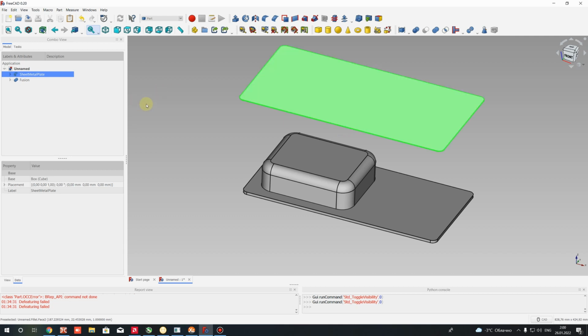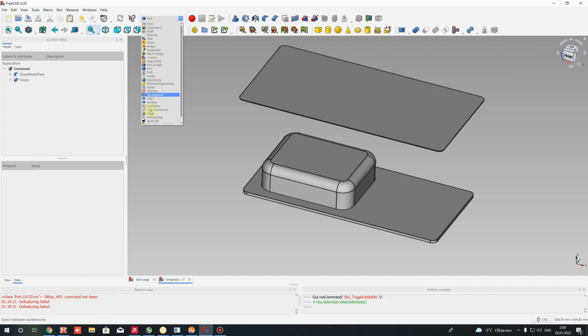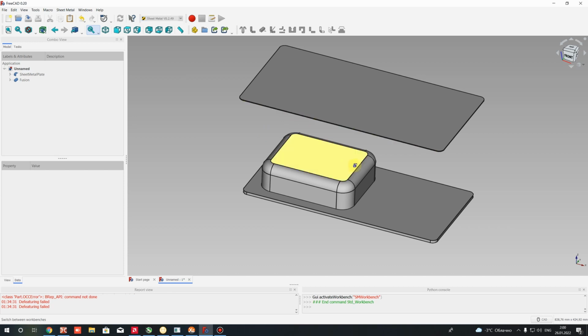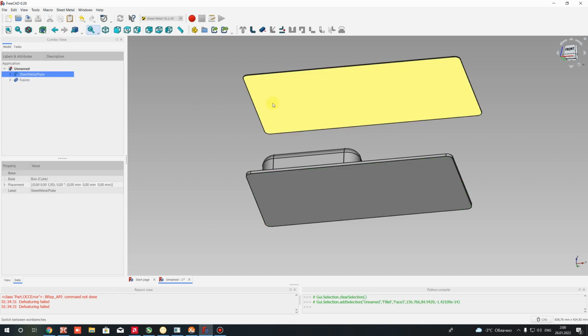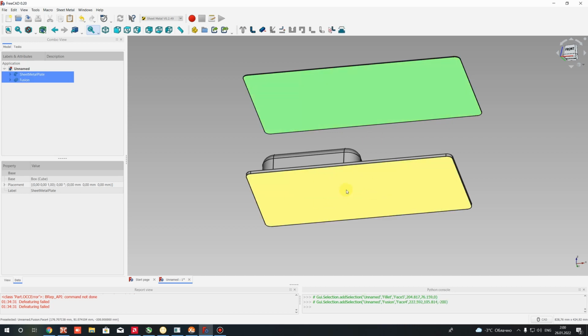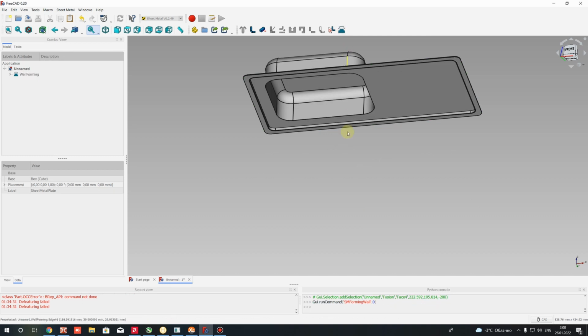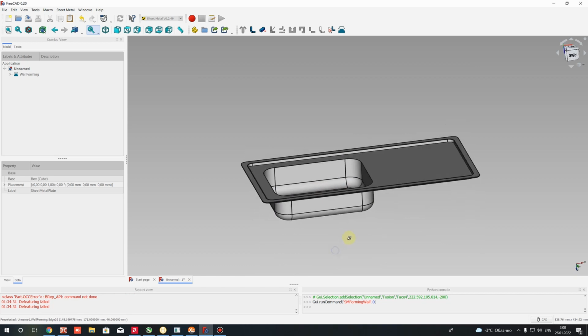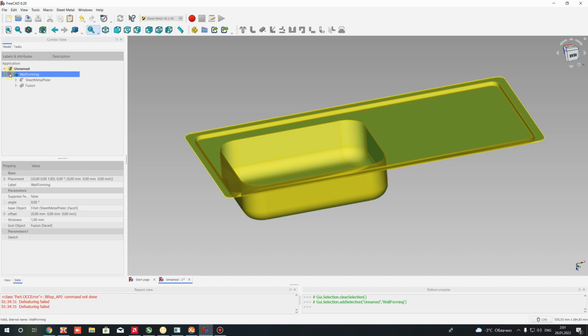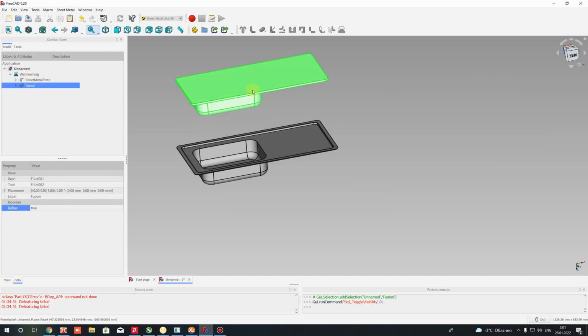Let's go. I will show you what the forming operation on a wall means in FreeCAD. So let's go to the Sheet Metal workbench. Let's choose this plate here. Maybe first we have to use this sheet metal plate. Second we use the face for the form, and press this operation, make forming in wall. Try it, and as you can see, you will get here the wall forming, using these two different bodies, this and the plate.